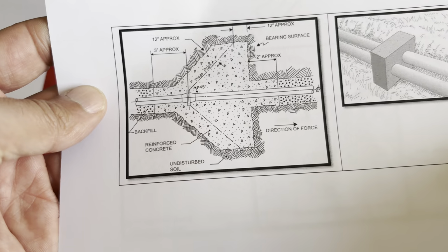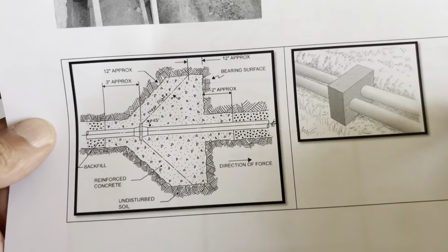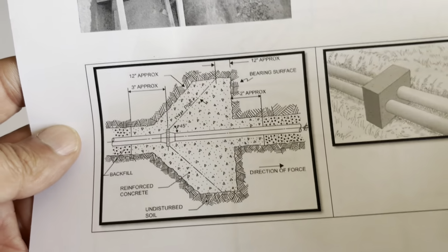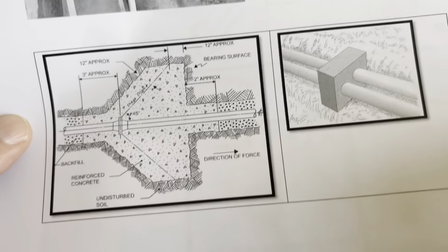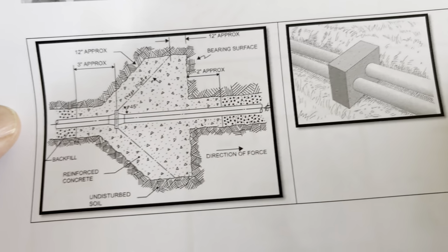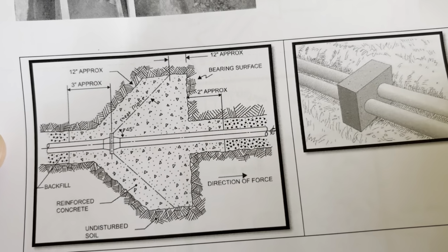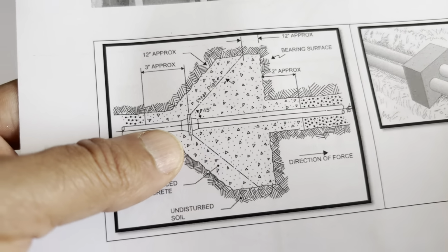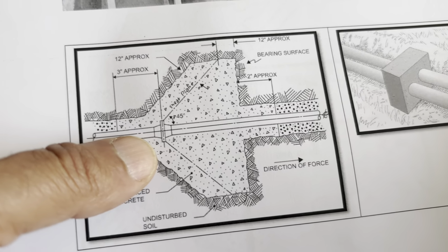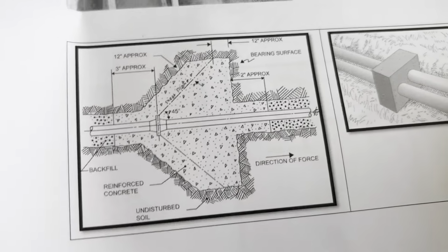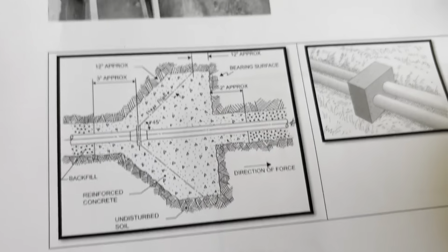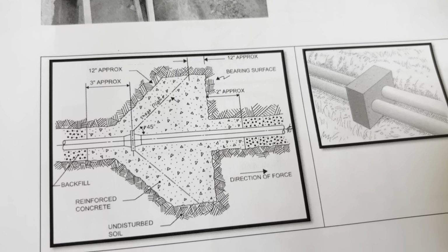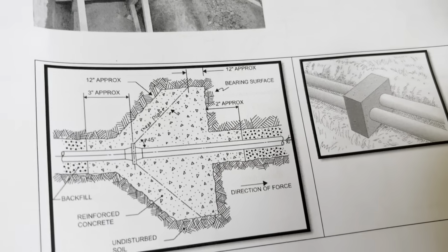These are some situations where we need thrust blocks. This is an anchor block, and definitely we have flanges, other changes, or stoppers in the fluid direction, and that causes a big thrust load and we need to take that load. And here same, we have some changes in the size of the pipe or the pressure, and we need to care about that. On the left side you see a big thrust block to react against the thrust load.